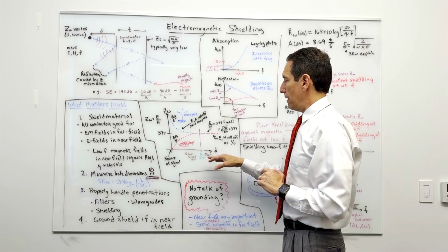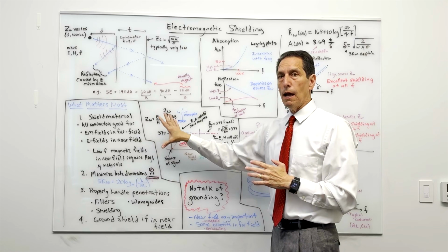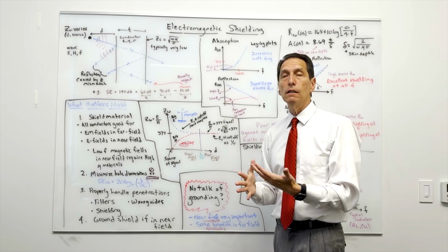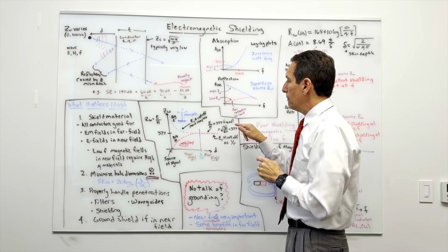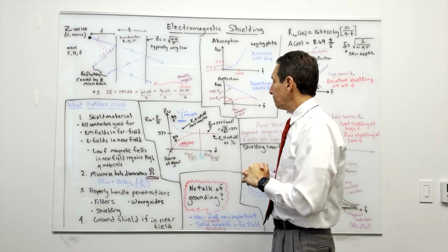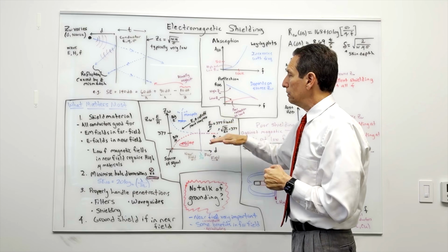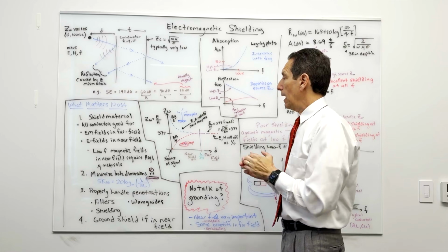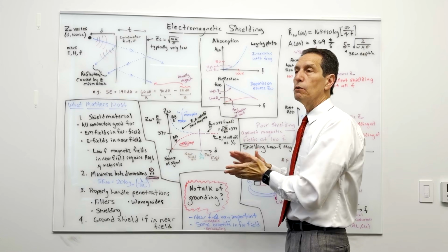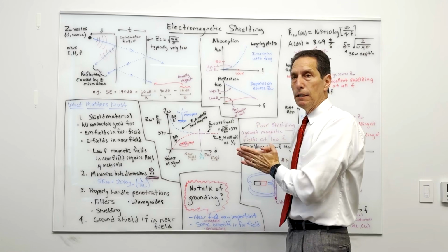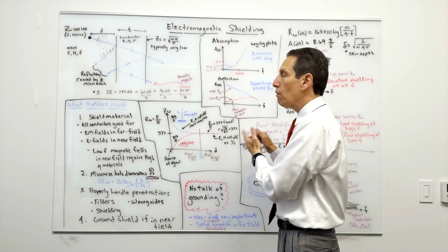And if you're further away than that, you're in something we'll call the far field, right? And if you're in the far field, it really doesn't matter what type of antenna source it was because you have a fixed E to H ratio, okay? That 377. And you can calculate that. It's just the dividing between the permeability and the permittivity, and you get the 377, okay? All right, so once you're in the far field, the ratio stays the same. And the electric field and the magnetic field both roll off as 1 over R, all right? So as R increases, the E and H both decrease. So if you double R, the E gets down by a half and H gets down by a half. It's just 1 over R, all right?